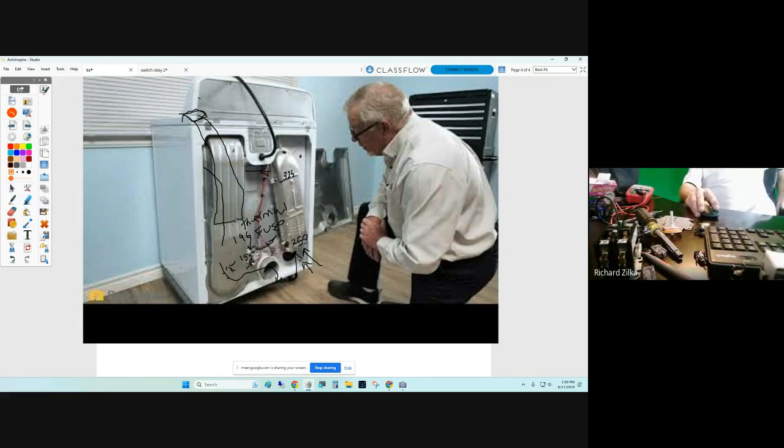But the point is, if that airflow is blocked here on the drum, we have seals. If the seal comes off the drum, we pull air in around here and not through the element. We don't get proper airflow of the element. If the customer pushes the machine against the wall and that flexible hose that comes back here is crushed, well, even if the fan's running, it's still not circulating enough air coming out. So this whole area is going to overheat because we have no air circulation.